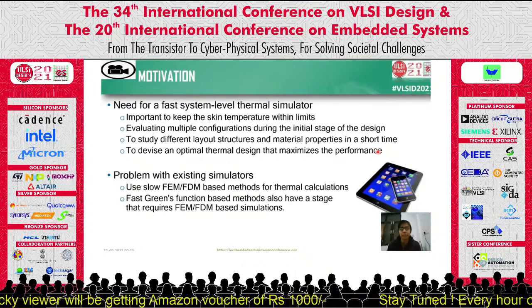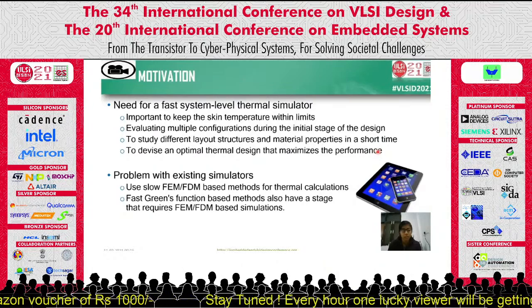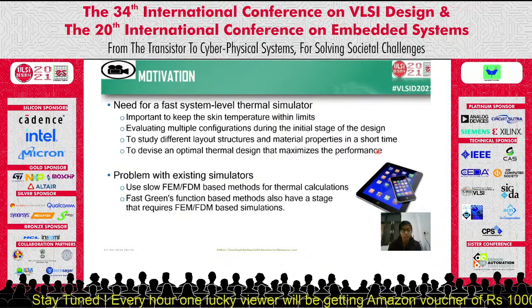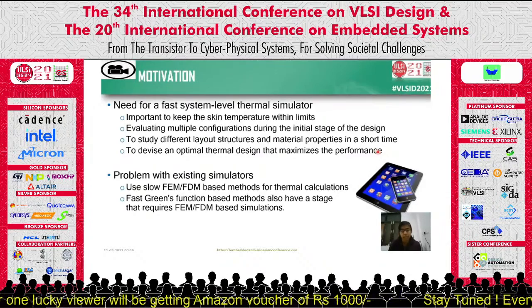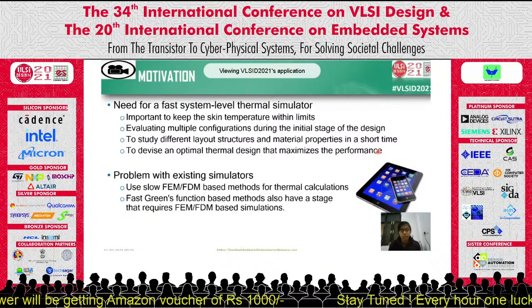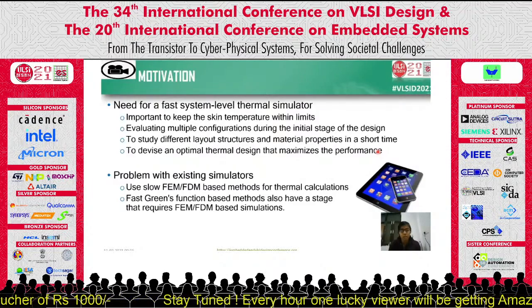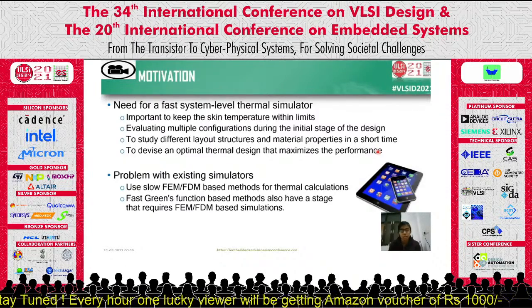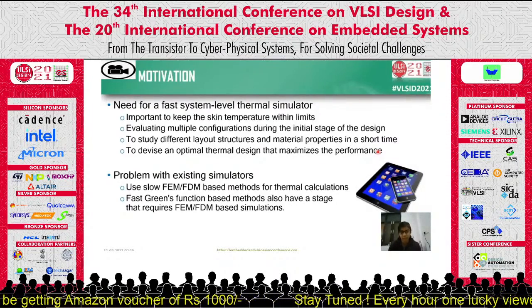thermal simulator is essential. Now, the problem with existing thermal simulators is that most of them use finite element or finite difference based methods, which are quite slow and hence not suitable for complete system analysis. The faster Green's function based methods also have a stage that requires FEM or FDM based calculations. In our approach, we have used Green's function based methods, but we derive the Green's function using simple polynomial expressions, and hence we avoid the slow FEM or FDM based stage during runtime.